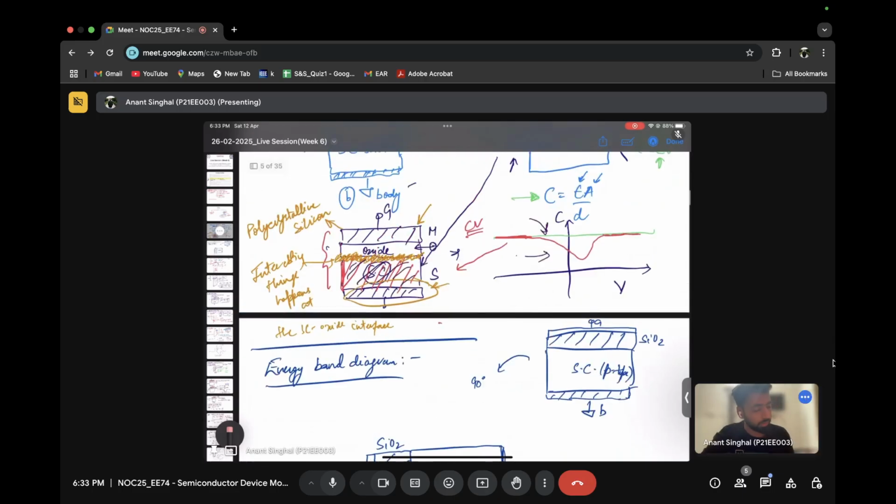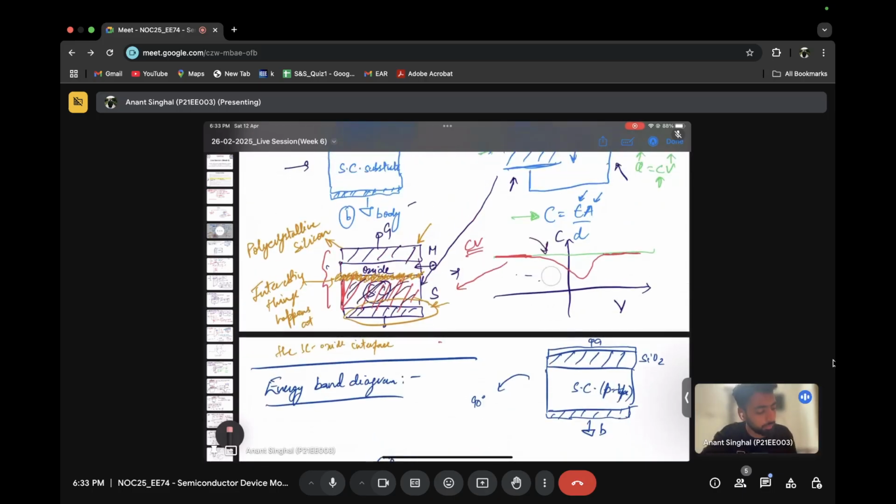Yes, yes. So you should know why this capacitor is looking like this U-shaped curve. The decrease in the capacitance is because it goes into depletion. It acts like two capacitors in series, which makes its overall capacitance decrease. And then in inversion, again we have an inverted layer that makes it equal to C oxide for the ideal case. This is what I want you to know.